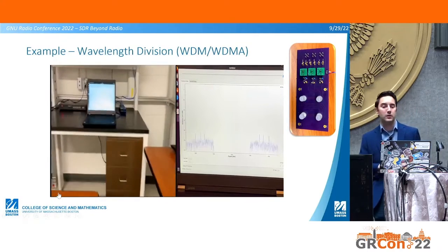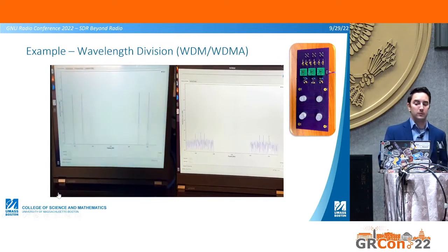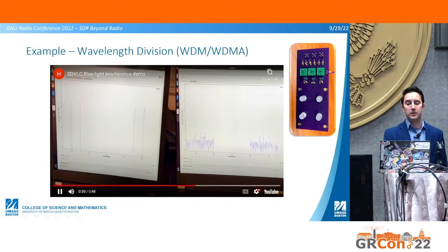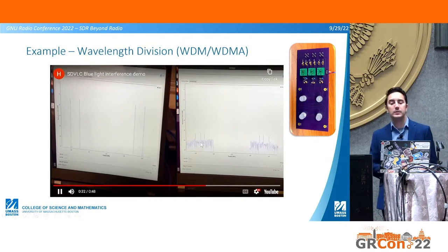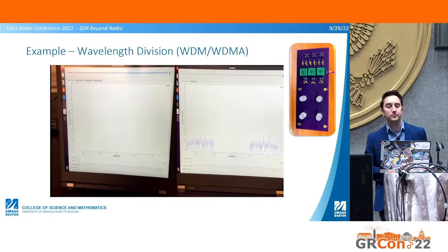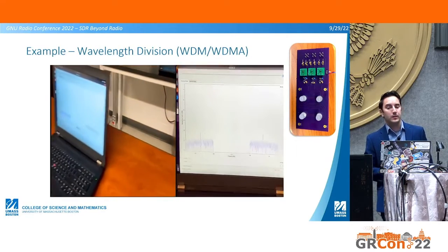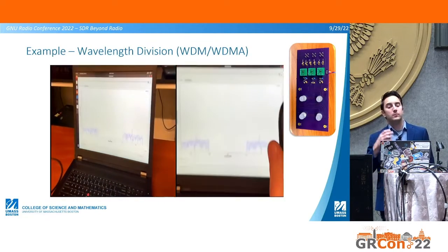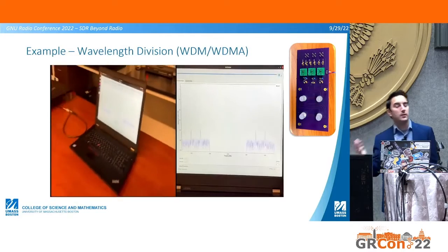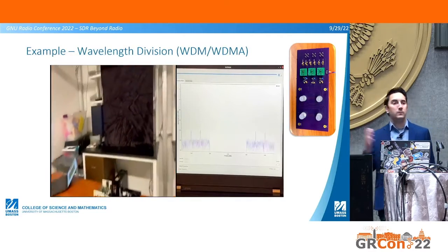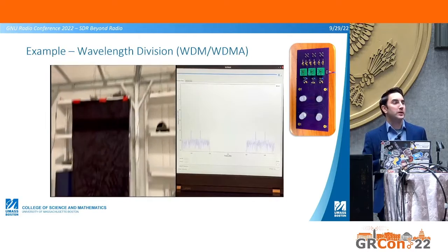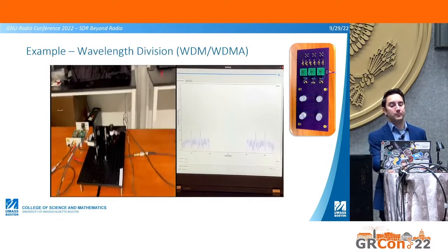from our blue channel to our red channel. And we'll notice that the received signal loses our intended signal, but keeps that blue interference as this goes away. And then if we come back over to our receiver, we're going to switch so that we're now looking at the red color channel. And we've mitigated that interference because it's still on the blue side. We're now transmitting on the red channel.